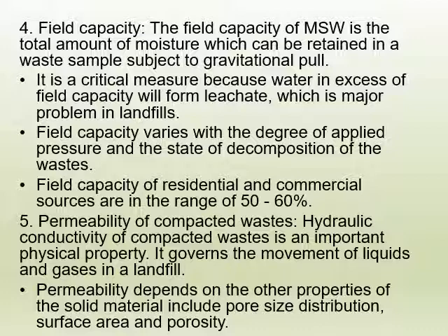Field capacity is related to moisture content which can be retained in the waste sample subject to gravitational pull. It is a critical measure because water in excess of field capacity will generate leachate, which is a hazardous liquid form of waste, which is a major problem in landfill.